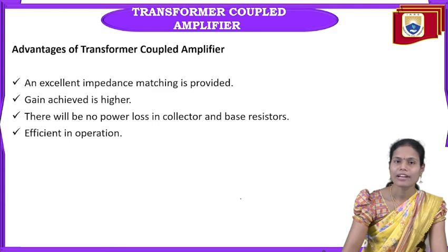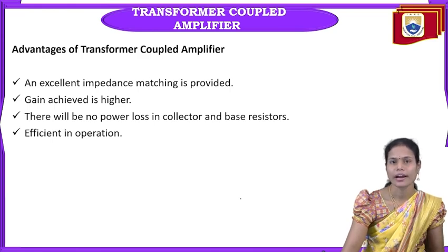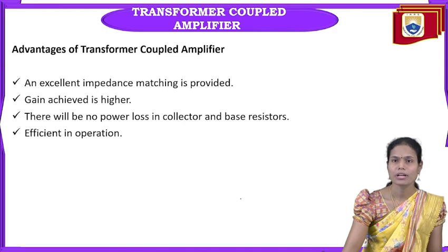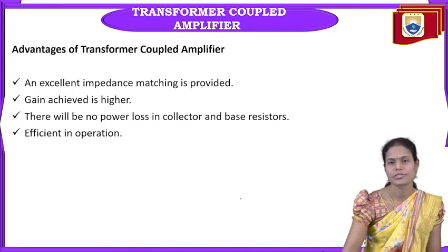While coming to the advantages of the transformer coupled amplifier, it provides excellent impedance matching between the stages, it provides high gain, and there is no power loss in the collector and base resistors present in the transistors. It is very efficient compared to the RC coupled amplifier or direct coupled amplifier.